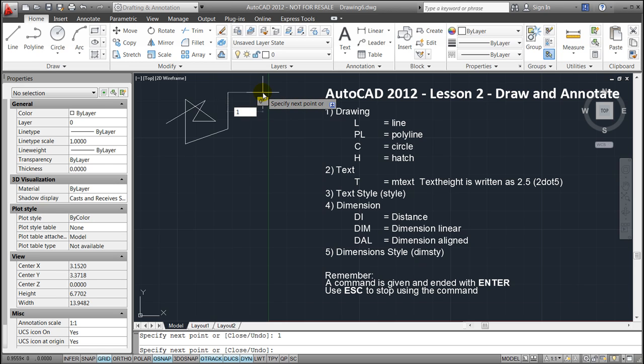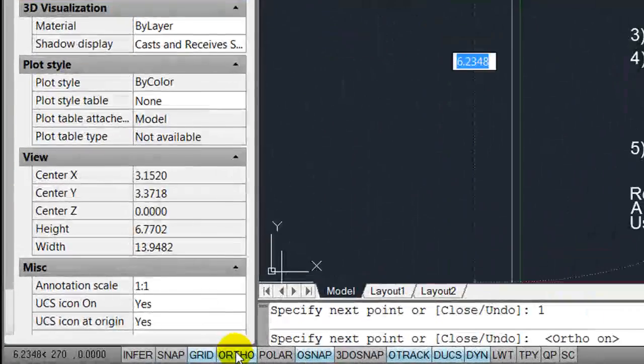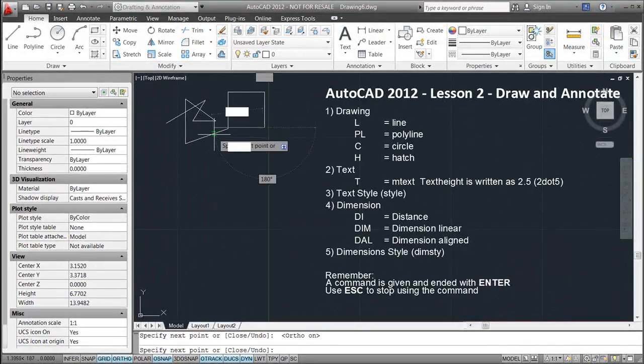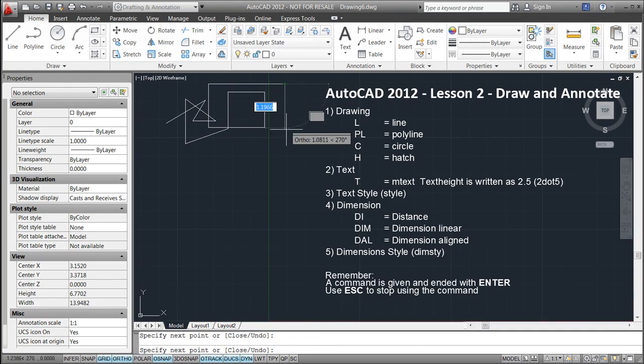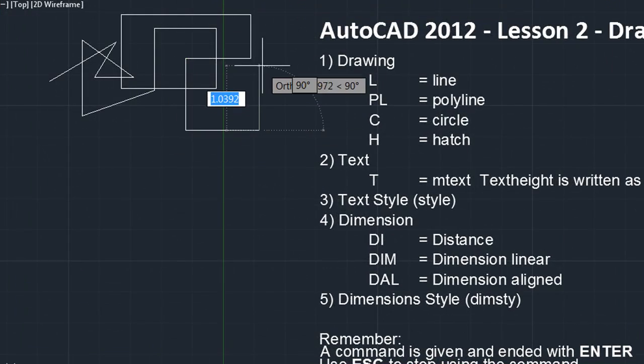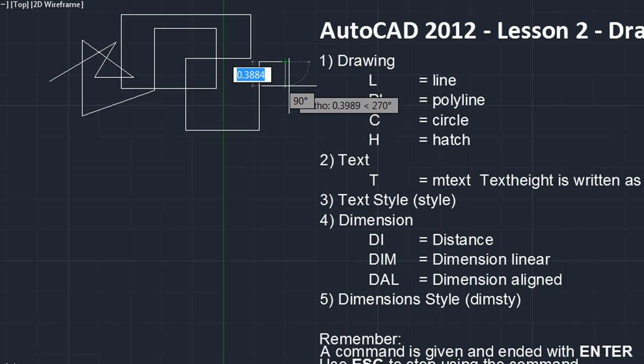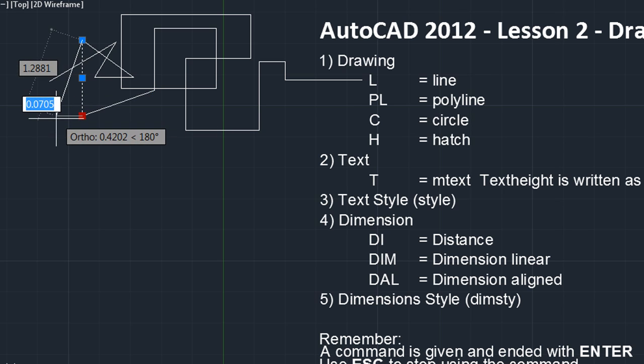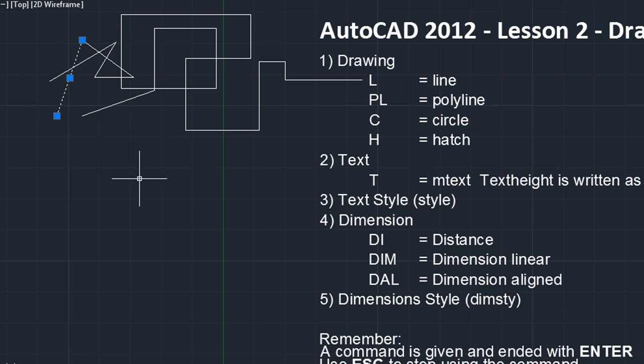or a combination where we turn on the auto mode, which only allows us to draw perpendicular lines, meaning lines placed in degree 0, 90, 180 and 270. We'll notice when selecting the lines that we can select them individually, and we also notice that when moving a vertex we so to say split the line, or the lines are being modified individually.